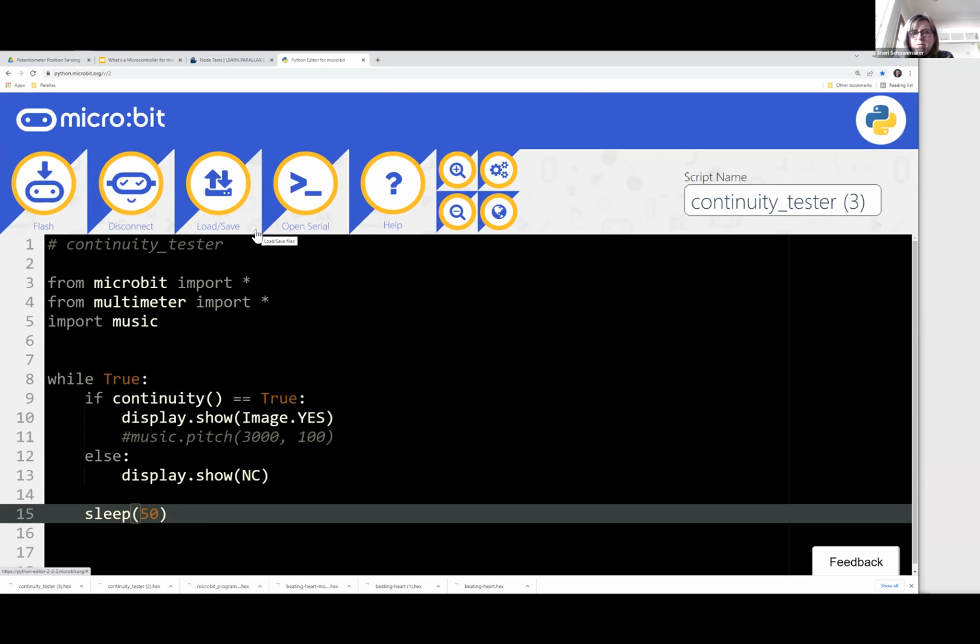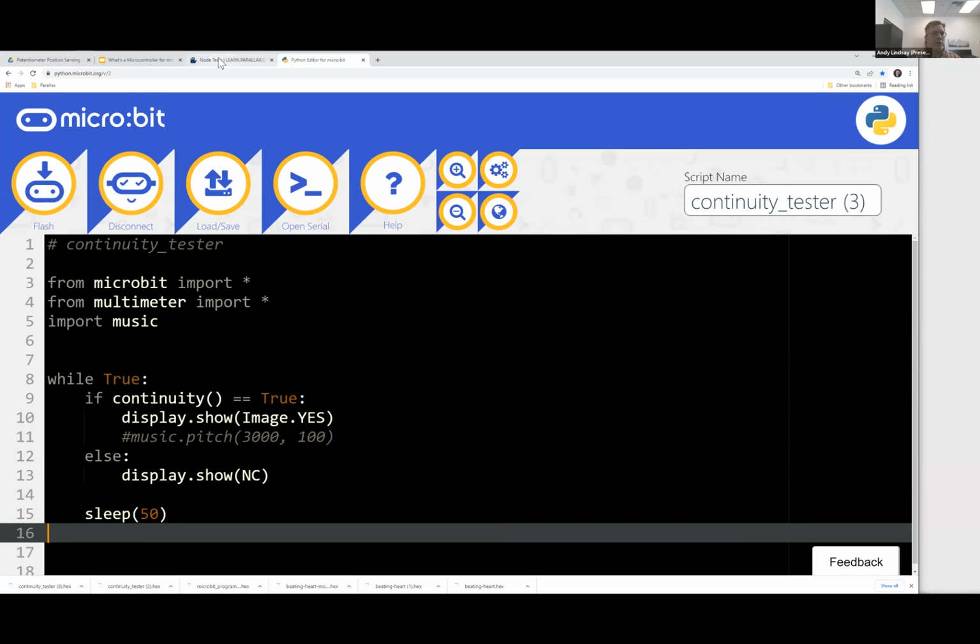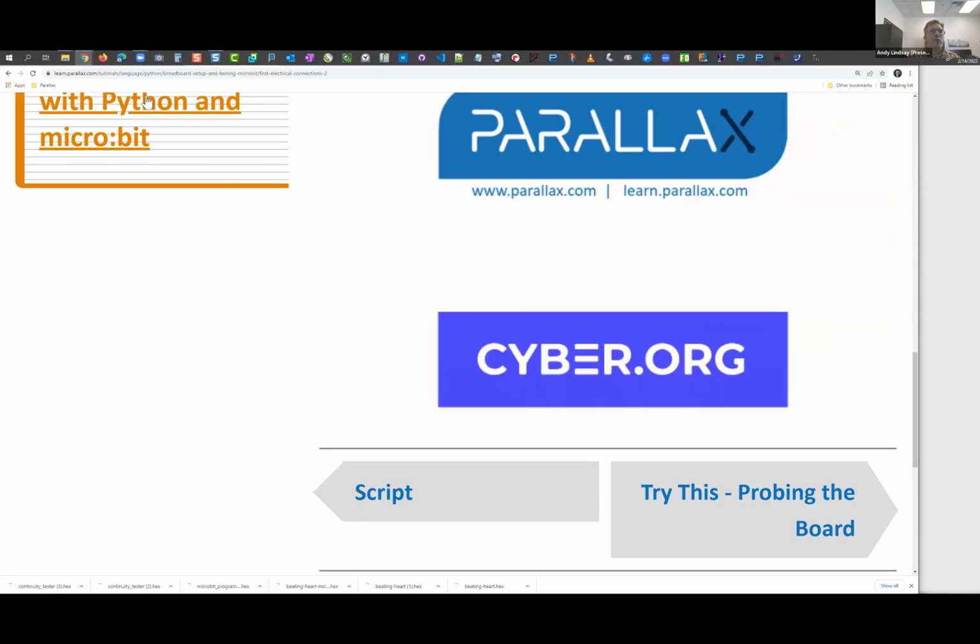But doesn't the Microbit 1.5 play some sort of sound some way? Oh, yes. If you connect something called a piezo speaker to the breadboard, then you can send tones to it. But the 1.5 doesn't have a built-in speaker. Correct. The 2.0 has a built-in mic, speaker, and a little extra program memory and RAM. And what else? Mic, speaker, RAM. The next thing will come to me at some point. I'll remember the other features that the 2.0 has.